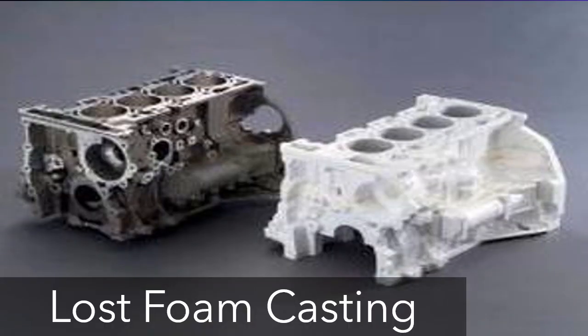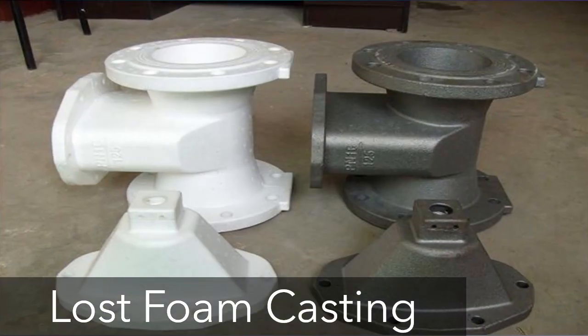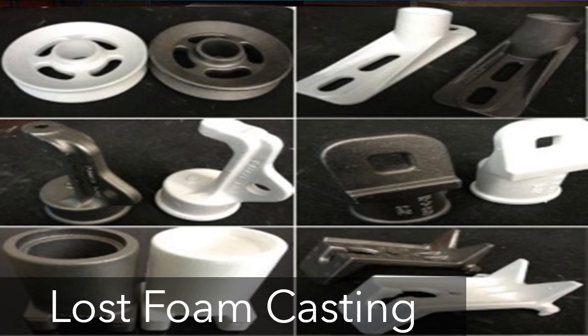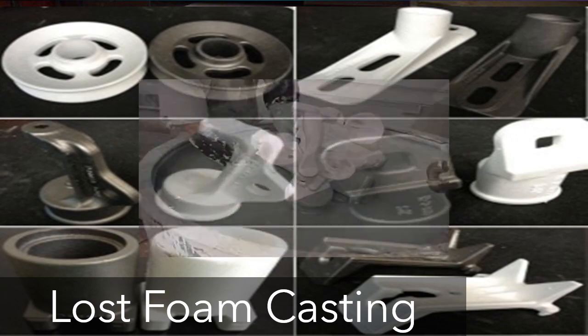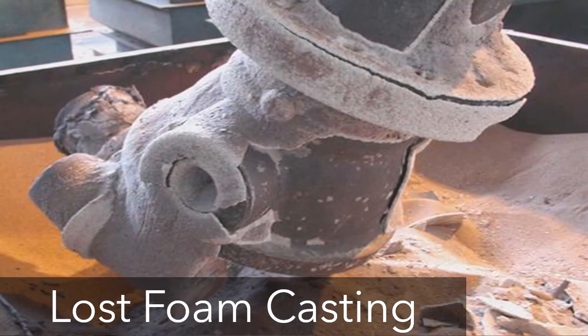Lost foam casting, also known as the lost pattern process, the evaporative foam process, the full mold process, and the expanded polystyrene process. The mold in this process is made from sand packed around a pattern made of polystyrene foam. The foam pattern evaporates. The polystyrene foam pattern includes the sprues, the risers, the gating system, and the internal cores if needed. The mold does not have to be opened into cope and drag sections.